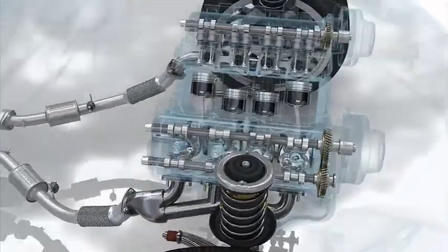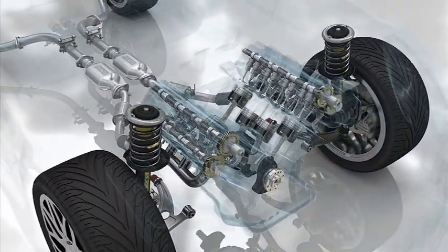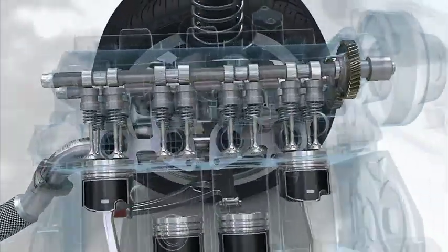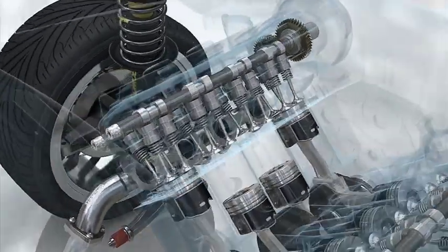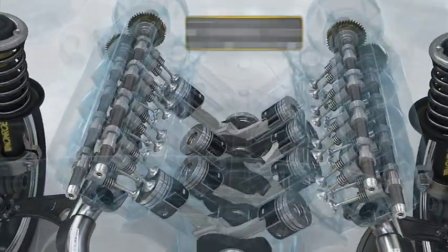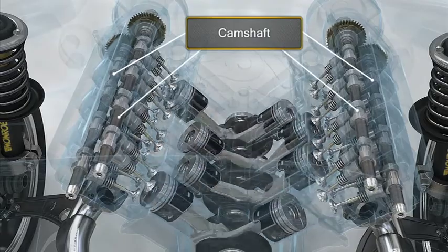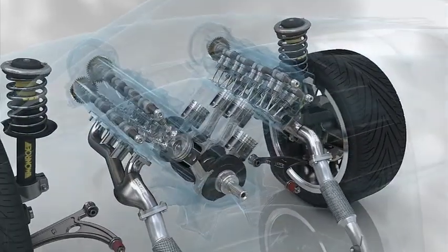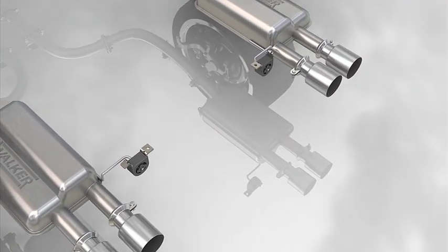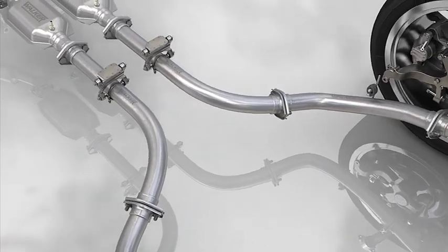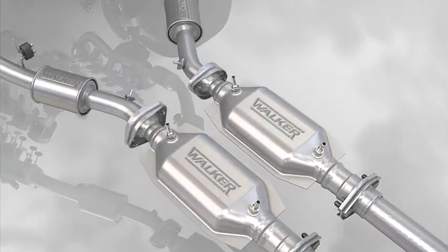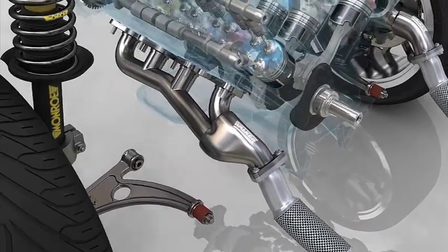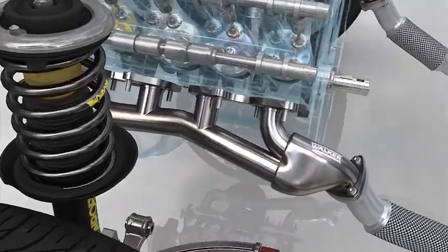Valve opening and closing times are controlled by the camshaft, a metal part designed by the engine manufacturer to operate at a certain level of back pressure. When the engine runs within this range, maximum engine performance is obtained with minimum energy consumption. The most effective way to optimize engine performance and thus lower fuel consumption of the system is to maintain exhaust gas back pressure values as stable as possible at any engine speed.